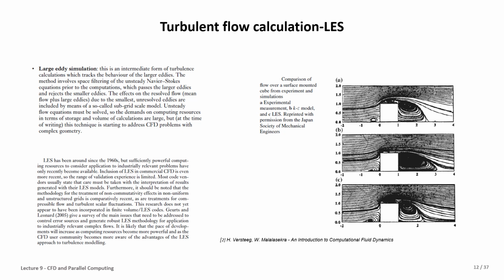When we have a 3D problem and we make a comparison between RANS and LES, the computing cost has a big difference, and it's very important when deciding which one to choose. However, we will see in some examples in the second part that sometimes using RANS will miss some details of the problem, for example about the geometry.